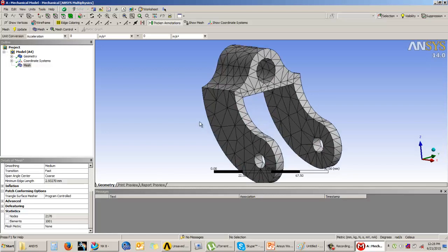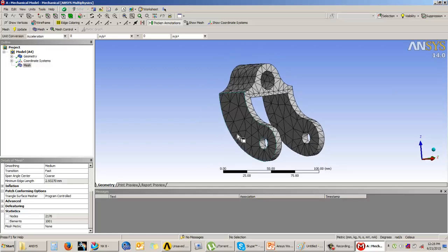Okay. So out of the two shapes, that is out of hexahedral and tetrahedral, hexahedral elements are much better and will give us much better and accurate results as compared to the tetrahedral elements. Hexahedral elements can fill a volume more efficiently than the tetrahedral elements. The tetrahedral elements will take approximately 5 to 6 tetrahedral elements to fill one brick.